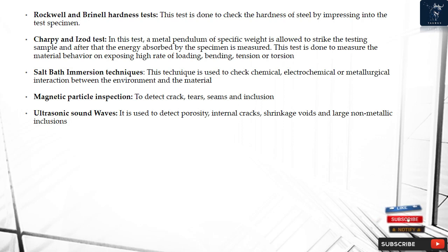Salt bath immersion techniques. This technique is used to check chemical, electrochemical or metallurgical interaction between the environment and the material. Magnetic particle inspection, to detect cracks, tears, seams and inclusions. Ultrasonic sound waves are used to detect porosity, internal cracks, shrinkage voids and large non-metallic inclusions.